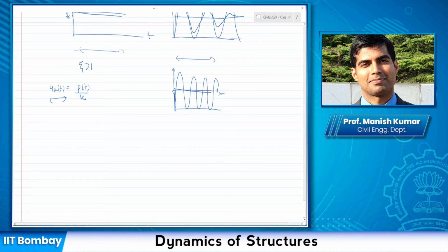Here, because I have non-harmonic or non-periodic motion, it's nothing like that. That would not occur, except for the one case we will discuss, where the loading is a sine pulse. It is not a harmonic loading, but there is still a possibility that if this time period, or time period by 2, matches with the frequency of the structure, then it might occur. Otherwise, no. Thank you, sir.